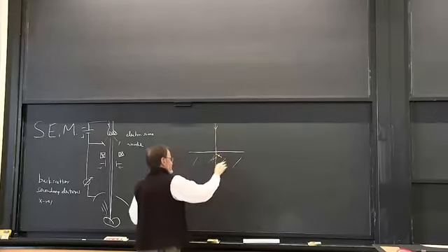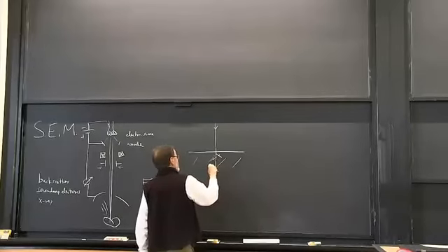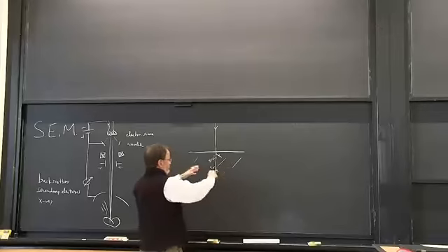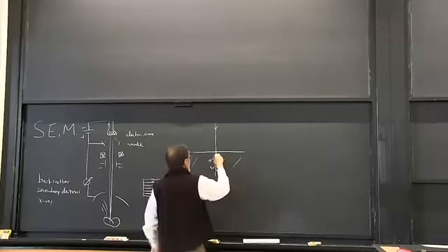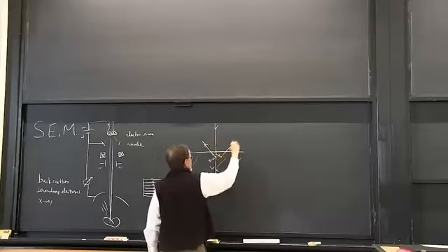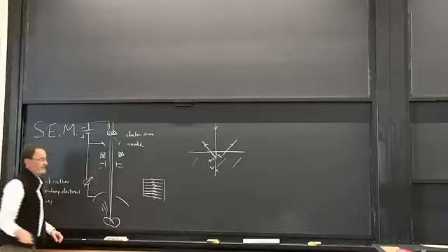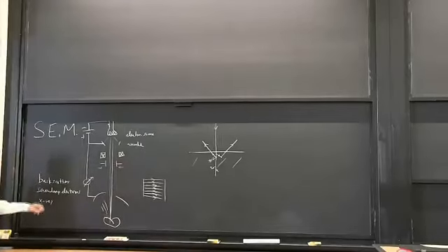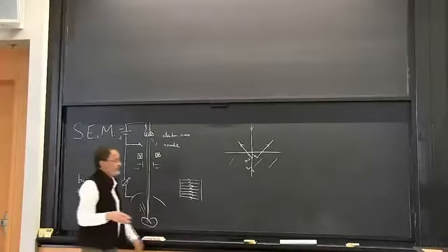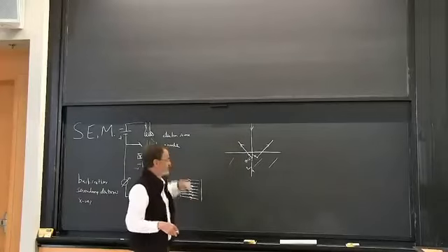So the first few are rather high energy, and then they get lower energy, and those guys bump into things, and most of those electrons just disappear in this object, but some of them that are near the surface escape and are measured by our secondary electron collector. And so basically what we're displaying is what fraction of the incoming beam actually makes it back out again.